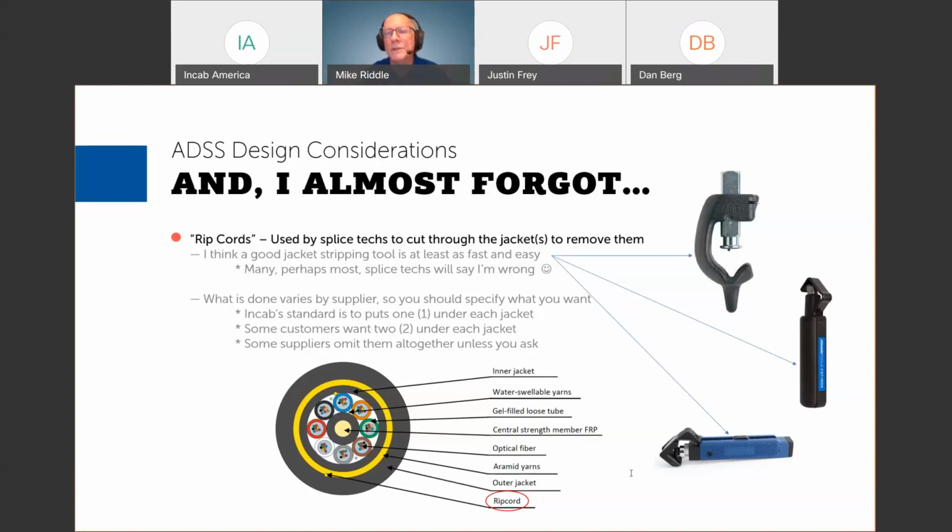And that's before I also would point out that there are some production practical matters with the tolerances when a manufacturer goes to make something. And I think those don't go favorably for the wedge type dead ends. So in my opinion, I don't like wedge dead ends. I think sometimes they might be appropriate on very short spans, and maybe in locations where you don't expect there to be heavy ice or wind loadings. But by the time I've put that many conditions on it, it's like, what's the real benefit of them?